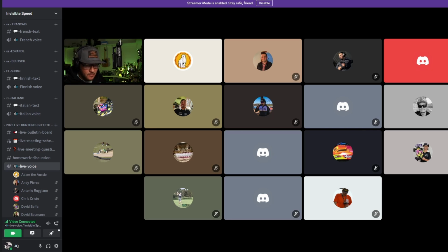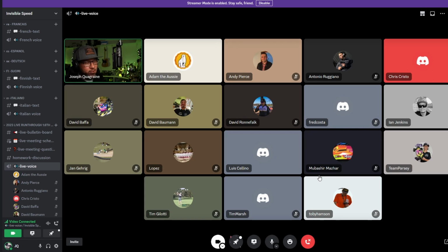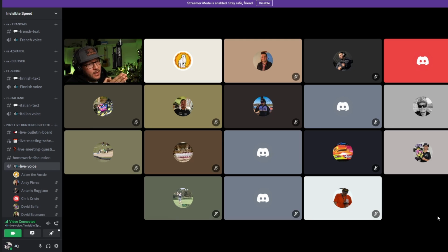I don't think I have the picture here now, but if you look at the jacking video, there's a part of the video where a car with a high roll center drives around the corner, and a car with a low roll center drives around the same corner. And then I captured them in the same position in the corner, and you can see clearly that the one car is high up and the other one is arms level. So visually, you can look at the car on the track and make a judgment of where the roll center is just by how it's handling in the corners.